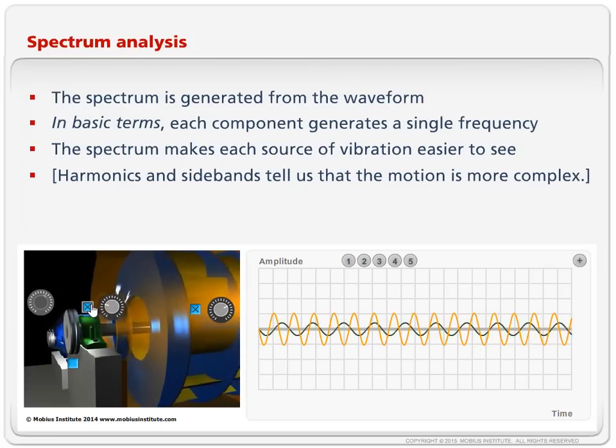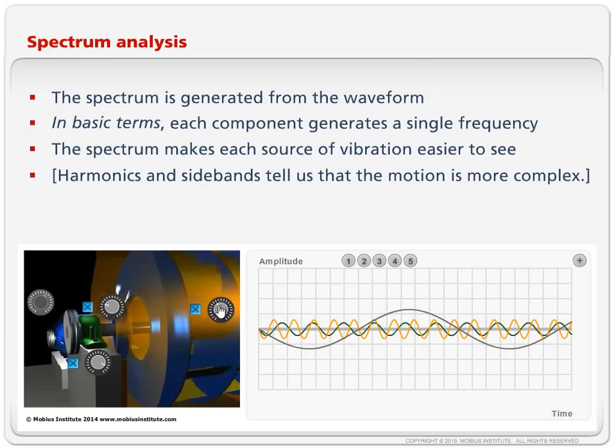So I've got my green vibration from the bearings, my grey vibration just from the shaft once per revolution vibration, and because I've got 10 blades, which the way I've set this up is a higher frequency than the bearing frequency, we can see more of a problem, less of a problem.